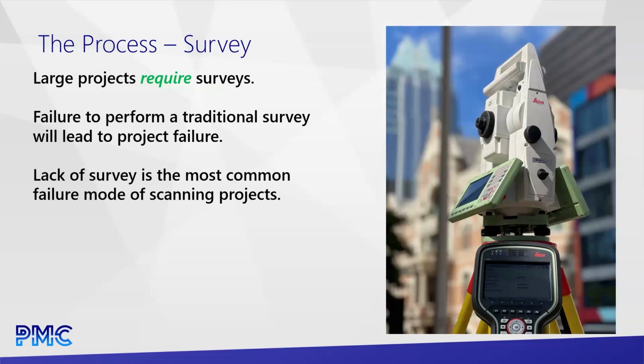If you do 1,000,000 square feet, let's say, and you don't use survey control, at an absolute minimum, it's going to take months to get that data properly registered together. Far more likely is it will never be accurate. There will be no way to ever make that data accurate.